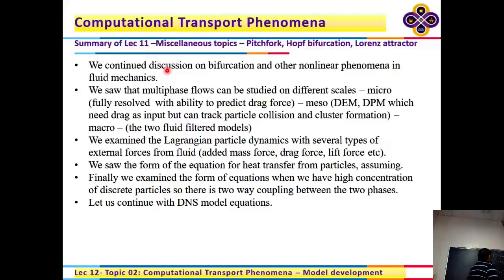But in the R momentum equation, once you do these things, you will find these are 0, but you will have dp/dr, and sorry, there will be one term here that's not 0: rho v squared over r. This will come out of the inertial term. That's a centrifugal force term. So when you expand this in cylindrical coordinates, you will get this. But the viscous term, again, will all be 0.